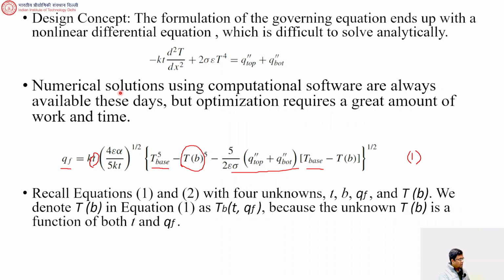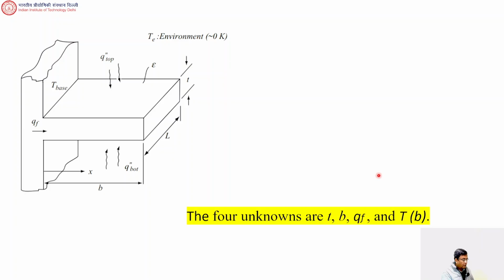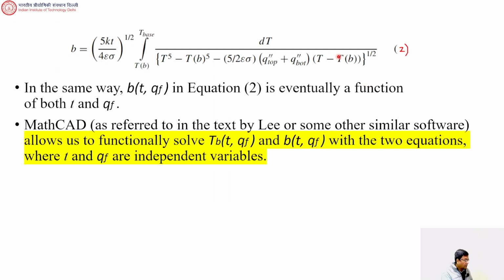these equations. Remember, this was the governing equation, and then on integration we got something like this. This is QF. QF again obtained as minus Ka dT/dx at the base of the fin, right? And we got this sort of expression. This is B, again, nothing new. So this is an example problem in the book in which the author has described the solution of this.